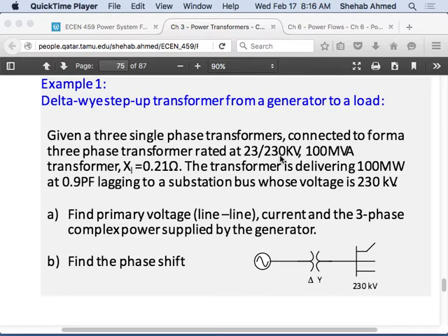Also 23 kilovolts divided by √3, phase shifted by 30 degrees. The line voltage is leading by 30 degrees, so you have to lag it, something lagging by 30 degrees, right? So line voltages lead phase voltages by 30 degrees. So here I'm given line voltage, and this is leading the phase voltage by 30 degrees. And it's square root of 3 greater than the phase voltage, right?